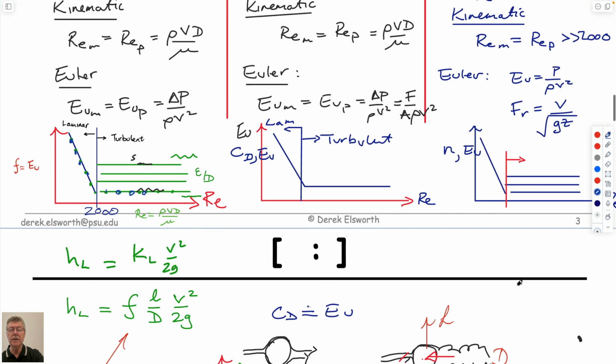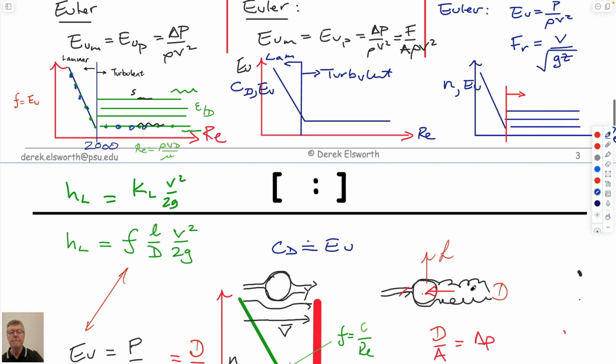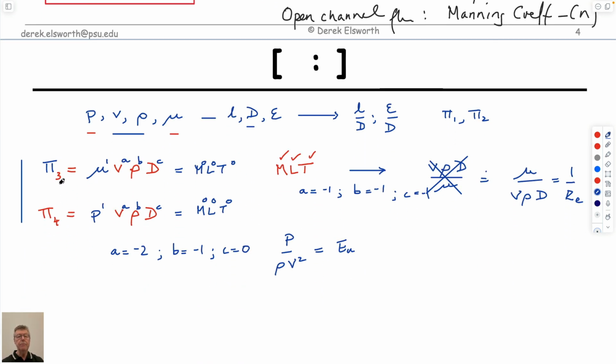So if you haven't looked at it yet, and I saw that lots of people hadn't looked at 9.3, dimensional analysis is just a formalism by which you can describe these non-dimensional groups. Typically, they come out to be some geometric factors, which give us the geometric similitude, and a kinematic and a dynamic factor, which give us the scaling in terms of a Reynolds number and an Euler number, almost always. But for different systems, you can describe this very formally. And so you can apply this also to other systems, not just to fluid mechanics. You can apply it to the aeroelasticity systems for the vibrating bridges that we talked about as well.